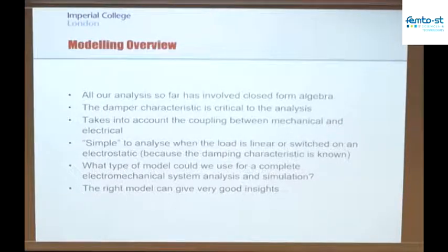So when we start building power electronics as the interface circuit between the harvester and the load, what we shouldn't be doing is designing and simulating that power electronics in isolation, because the behavior of the power electronics is going to affect the behavior of the harvester, which is going to affect the electrical output of the harvester, which is then going to affect the behavior of the power electronics. So you can't really do these things completely in isolation. You can get some indication, but you really need to be analyzing complete systems.